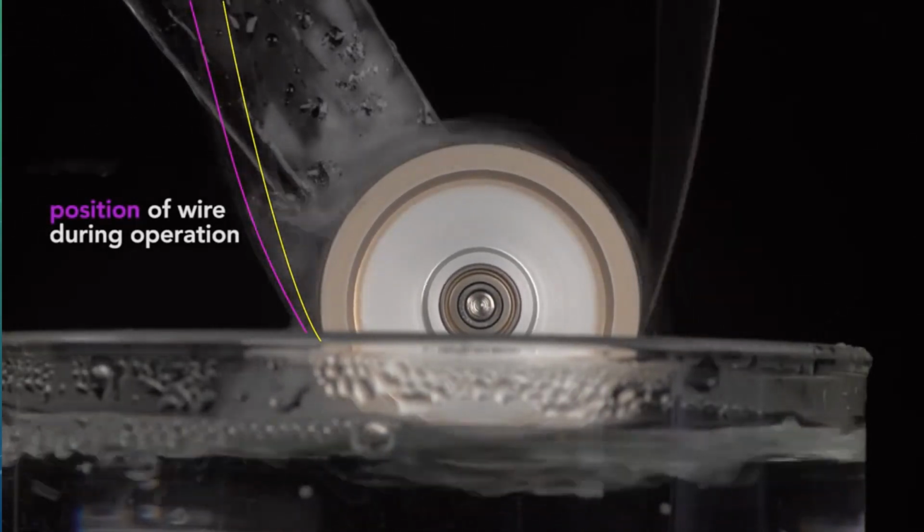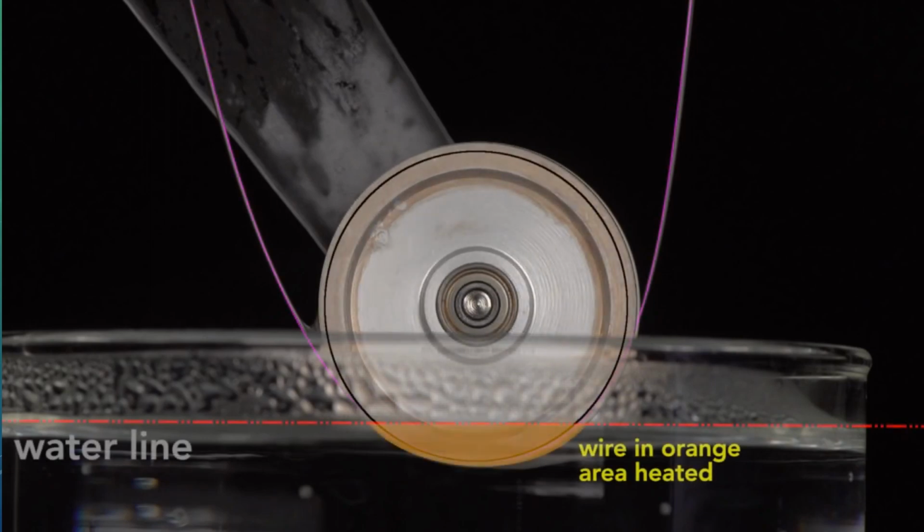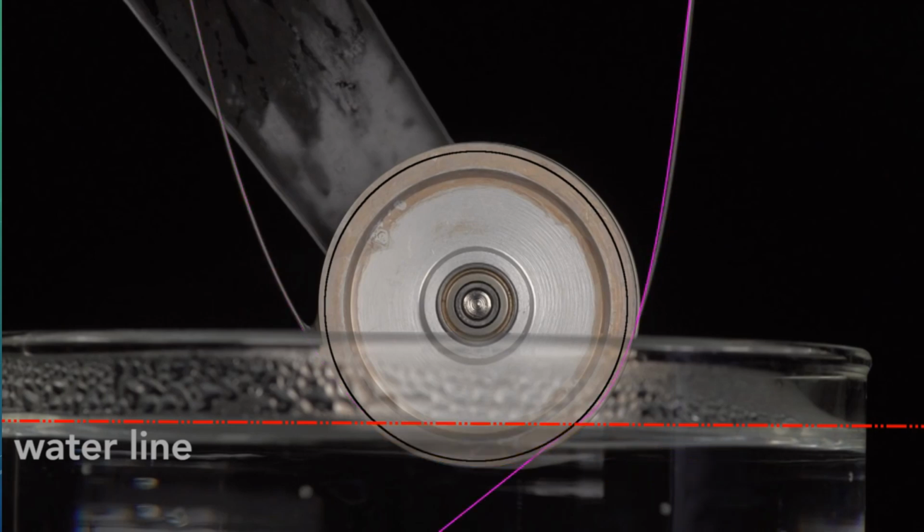This happens because when the bottom wheel comes into contact with the hot water, the section of the wire highlighted here in orange is heated. If it were not in a loop, then the wire would be straight like this. But because it's in a loop, as it tries to straighten, it exerts a force on the wheel, which causes it to turn. Let's break this down.